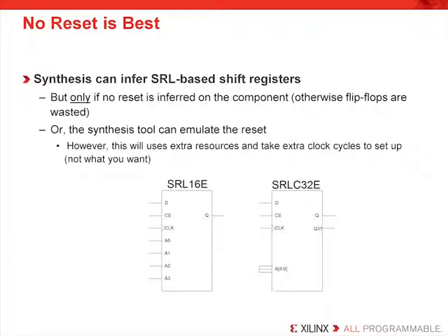In one customer design, there was a global set reset throughout everything, and the shift registers could not be inferred. The designers were already inferring about 100 shift register LUTs and were doing a good job making use of the dedicated resources. But by removing the global set reset, they obtained over 150 shift register LUTs. This, of course, saved power and saved CLB flip-flops.